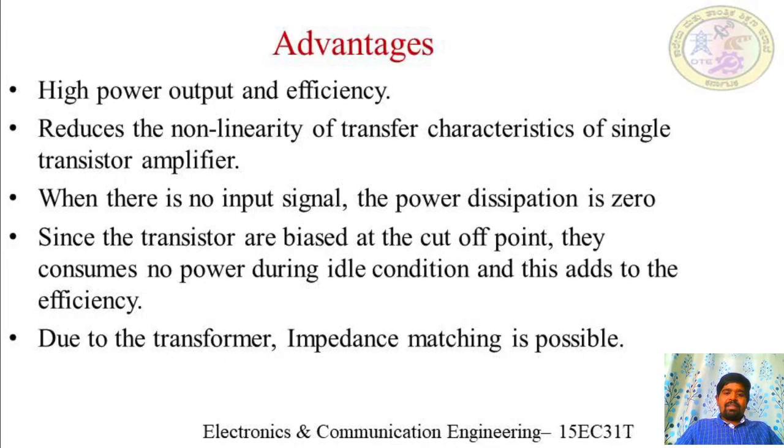So what are the advantages? High output power and efficiency. As we already discussed, one of the reasons why efficiency will be high is that when there is no input signal applied, none of the transistors is on, that means the transistors will not take power from VCC, so there is no power loss and efficiency will be high. This also reduces the non-linearity of the transfer characteristics of a single transistor amplifier, because in a single transistor amplifier non-linearity will be there. So that problem we are overcoming here.